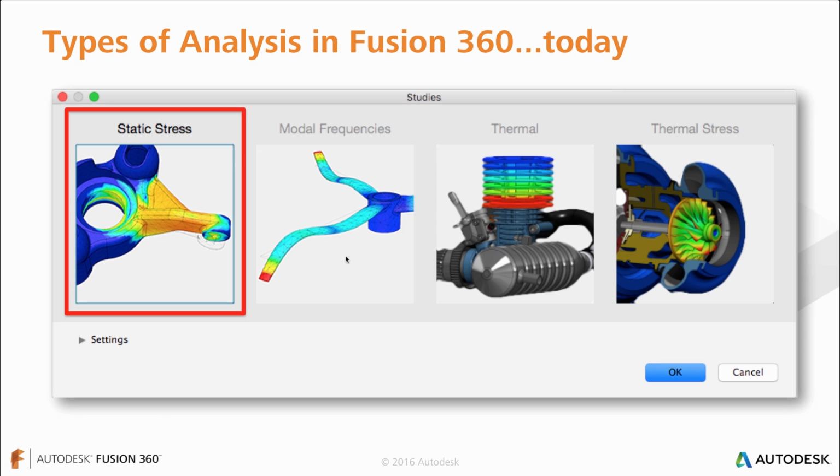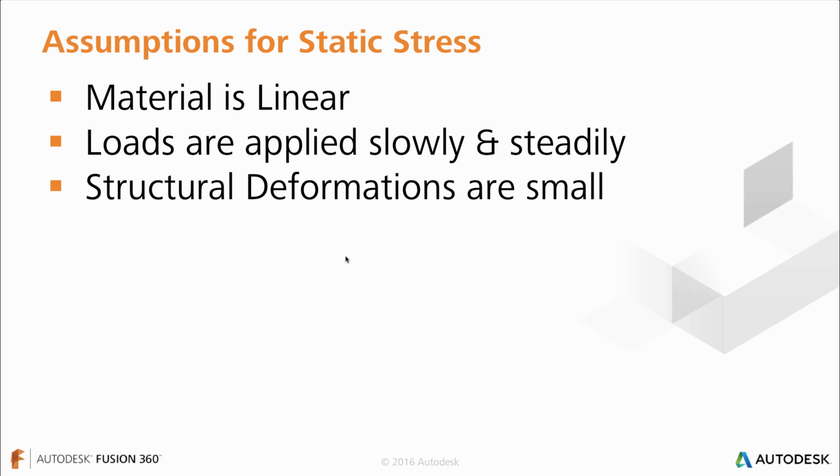Like I said, though, what I'm going to be talking about for the theory portion, for this first portion, is really related to static stress studies, because it's a good building block. I mean, once you understand how to run a static stress study and you understand the basics behind this type of study, you can use that same approach in most every single other analysis that you end up doing down the line. So keep that in mind. So assumptions for these static stress studies. The material is going to behave linearly, and I'll talk about that in more detail on the next couple slides. Loads are applied slowly and steadily.